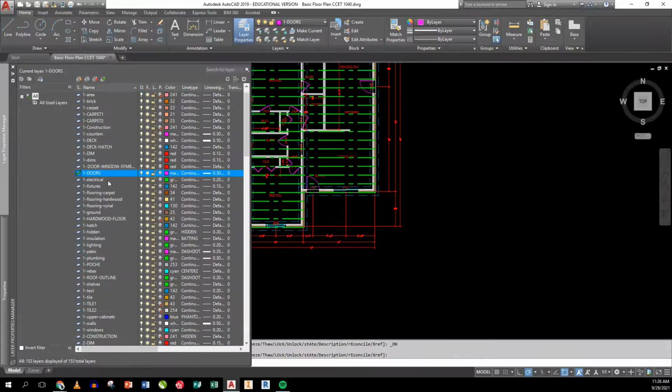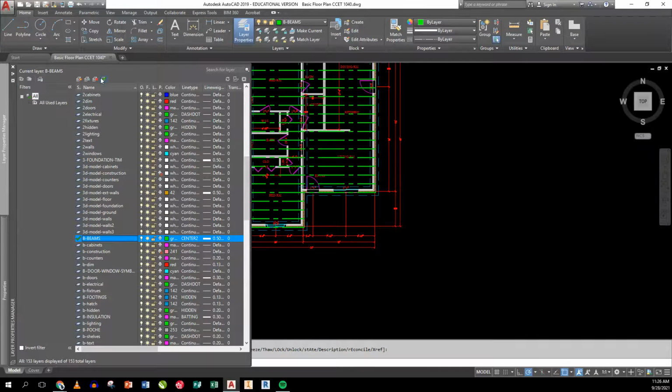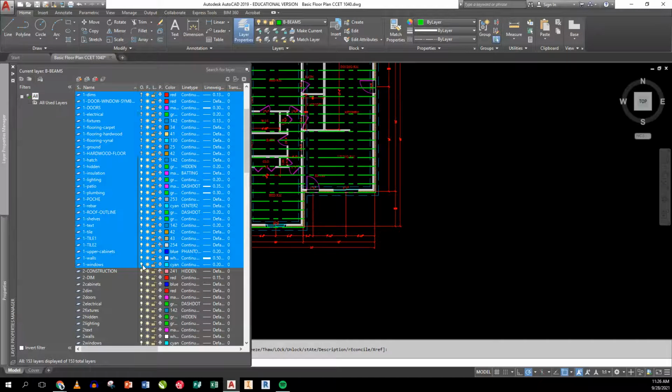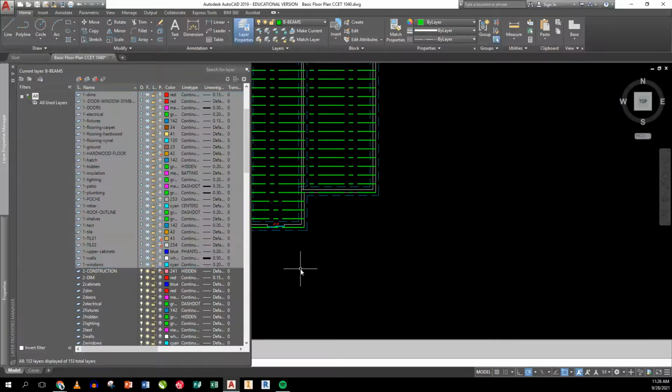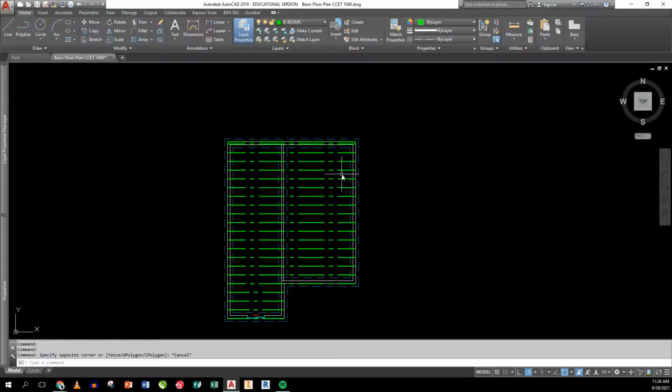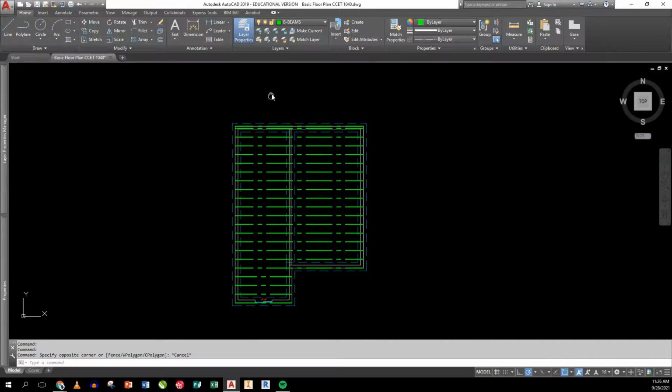Okay, that's because that way when I do something like this, and I go in here and say, okay, I want all of my first floors, let's go down here to B. I'm going to say my B dims is going to be my current layer. And I come up here and I highlight everything from here, and I hold my shift key down to here and tell all those to be off and frozen. When I go like that, that means I don't end up getting my stairs by accident, and my stairs stay locked and on. Okay, that way I can tell where they're at on both floors, and I don't have to worry about drawing a wall on top of one of them or putting my stairs in one spot on one floor and a different spot on the upper floor. So that's it for layers and putting in the foundation.